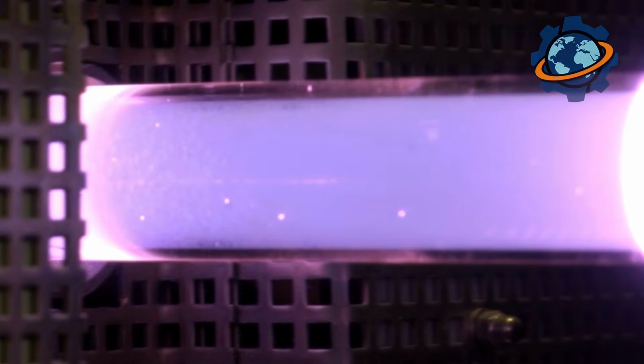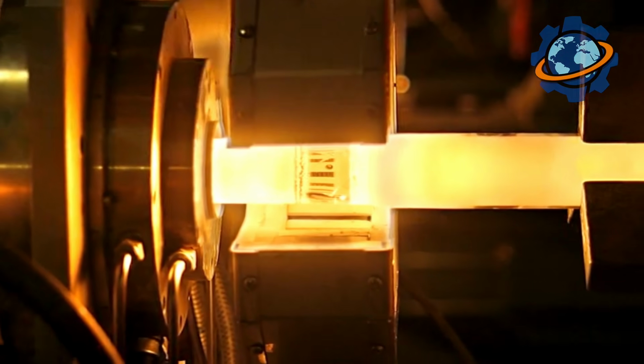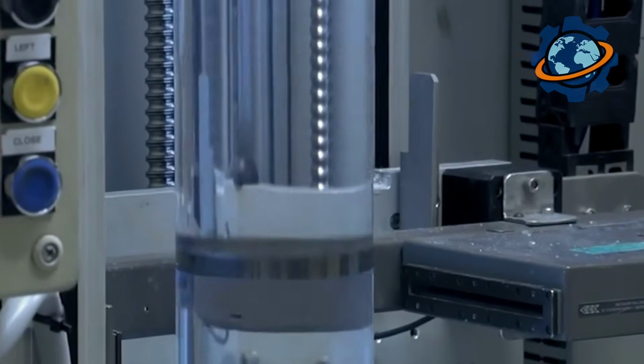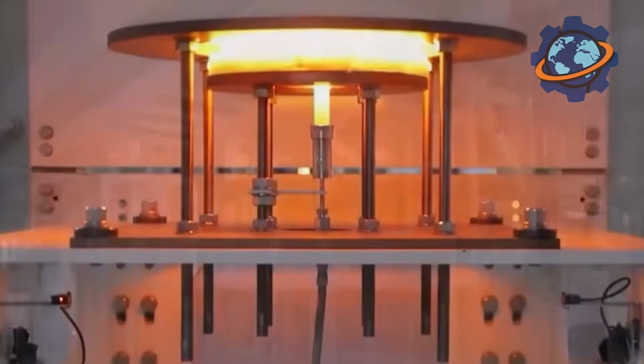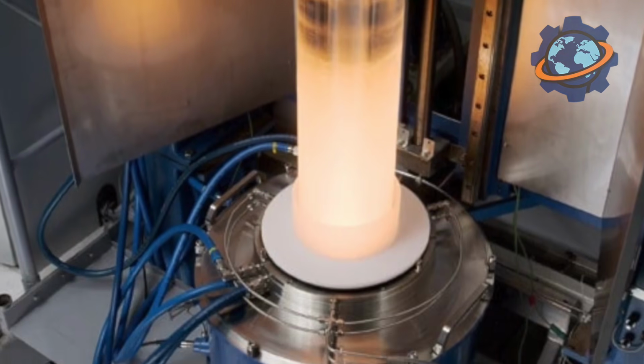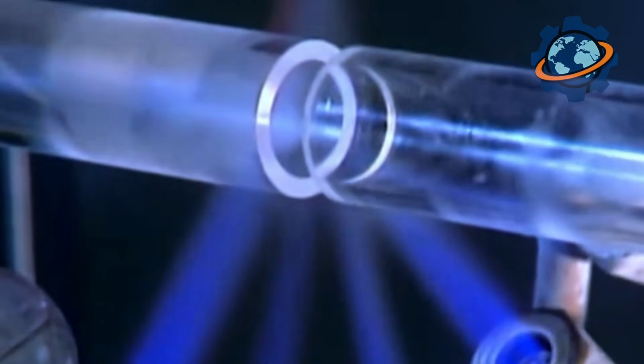These vapors hit the inner surface of a transparent tube, which is heated very intensely. When the vapors touch the hot wall of the tube, they deposit and turn into tiny droplets of glass, like dew collecting on leaves in the morning. Gradually, these droplets collect, layer by layer, until a thick layer of glass forms inside the tube. Then this tube is heated even more intensely, and it collapses into a dense solid rod, and this is our preform.